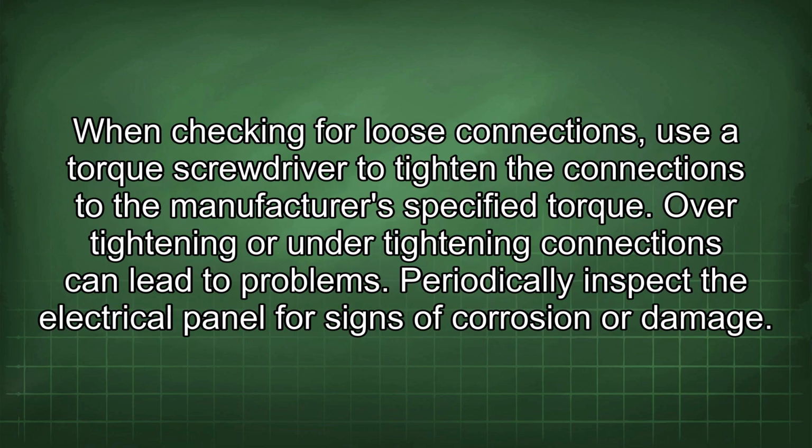When checking for loose connections, use a torque screwdriver to tighten the connections to the manufacturer's specified torque. Over-tightening or under-tightening connections can lead to problems.